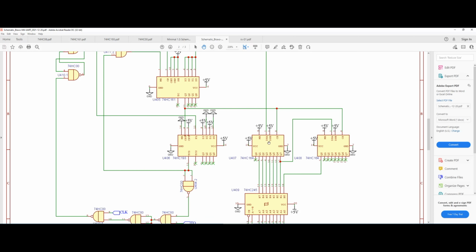All right, so as you can see, we actually have 2 serial inputs into those chips. However, these serial inputs are internally AND gated, meaning they are going to an AND gate inside the chip. Since we are just coming from one serial link here, we could tie the other one to high, so that whatever signal comes on the DSA will be shifted to the outputs, and we could just tie the DSB to high and ignore that. We will be using only one serial input here. And of course, just like the previous circuits, these 2 chips are cascaded to each other, which we're going to get into in a minute.